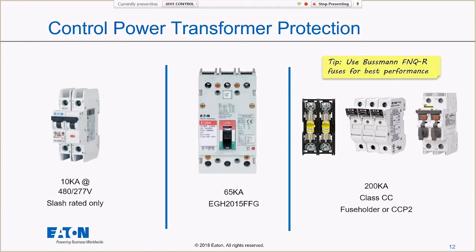You know, they can be used anywhere you put fuses in your circuit, for Class CC fuses for this specific one. But I really do think it's a great thing to use in front of your control power transformers, just because of how often that is used for switching capability. So to use it there as a switch, it gives it that rating to be used as a switch. Really great product. DIN rail mountable.